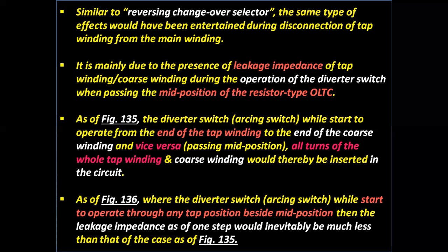As of figure 136, where the diverter switch, that is arcing switch, will start to operate through any tap position beside mid position, then the leakage impedance as of one step would inevitably be much less than that of the case as of figure 135.